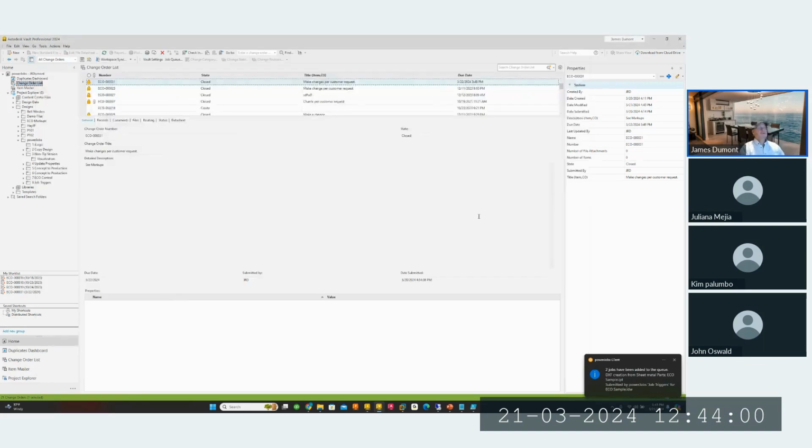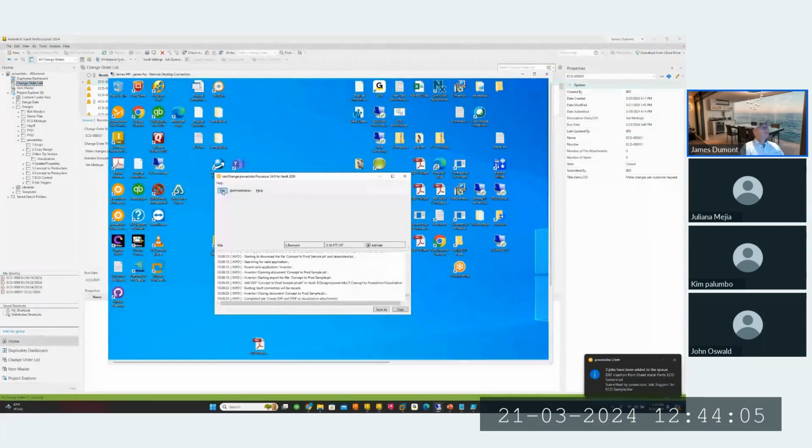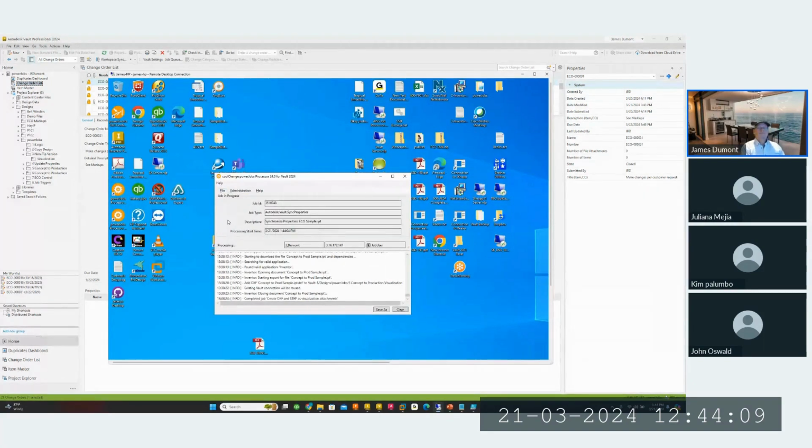That's all I have to do. Once I wait for the file to get processed, revision history will fill in automatically. It'll put the ECO number in there for me. The ECO contains all of the notes, anything that's relative to that change. Do the markups, whatever you need to do in the ECO.